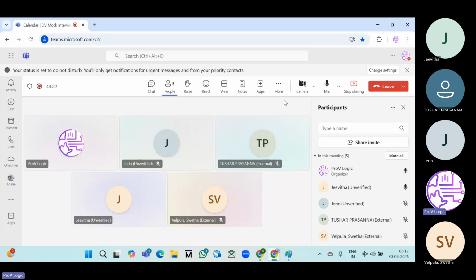Whenever we use assign, left hand side variables must be declared with the wire data type. Right hand side variables must be declared with wire or reg data type. Okay. What about for procedural always statement? For always, we must use LHS side reg. RHS side?